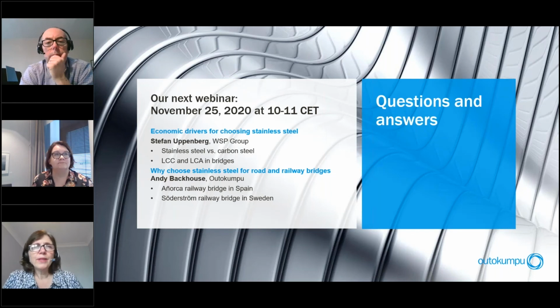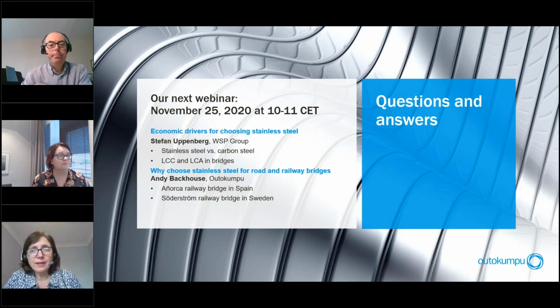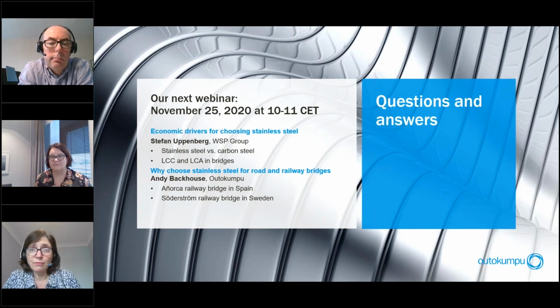Well, in my presentation, I showed that the thermal expansion of Duplex stainless steel was very, very similar to that of carbon steel, 13 as opposed to 12 times 10 to the -6 per degree centigrade. So that isn't likely to have led to any significant problems. For the austenitics, yes, it is higher, and I think you just need to take it into account in detailing. I mean, the metals are joined regularly, so it's not an insurmountable barrier, but it's something you need to know about and take into account.